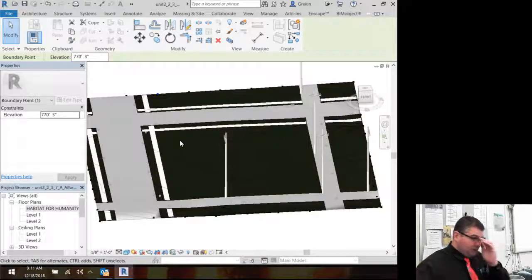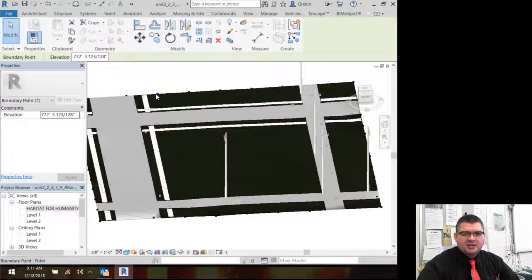So if the highest point of my front yard over here is 772 feet, and over here it's 771 or 770 feet, our yard slopes from the front to the back, right? You guys determined that. So it's likely that my front yard here, within my boundaries, is a little lower than what it is along this line of points, right? Can we assume that? Probably around 769, somewhere in there, right? So I want to kind of guess what my points should be. I can always change them later. So let's go ahead and,